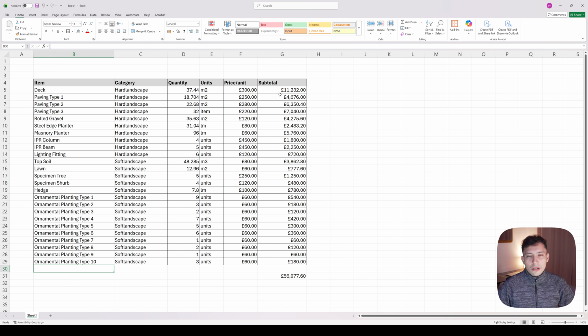And now I'm going to show you a trick so you can organize this data to your own needs. For doing that, I'm going to show you a command which is really handy when you want to organize the information in a schedule. For example, let's say that you want to organize this by price, the cheapest one at the top and the most expensive ones at the bottom. So for doing that, I'm going to create here another header, and this one is going to be called cont. So cont is going to be basically the way this information is arranged at the moment.